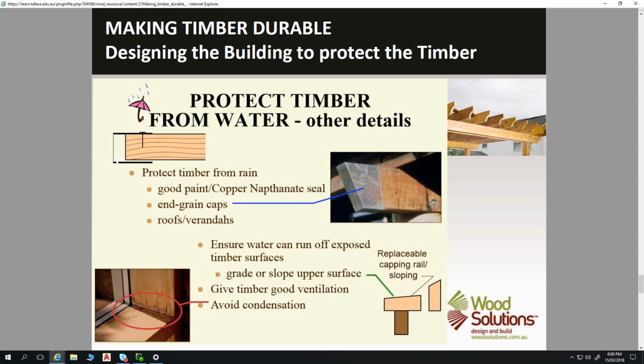You get water, of course, running down the rafter or tracking down the rafter, and it sits there. And when enough of it sits there, you get a drip. But when you don't get enough for a drip, it sits there continuously and then soaks in the timber, and you'll end up getting a rotted portion to the end of your timber. Has anybody seen that before?